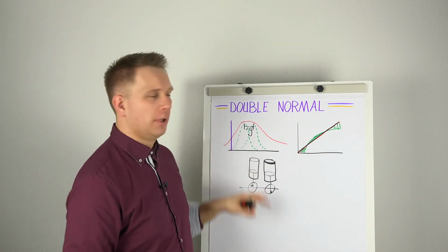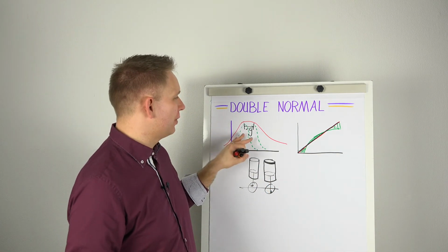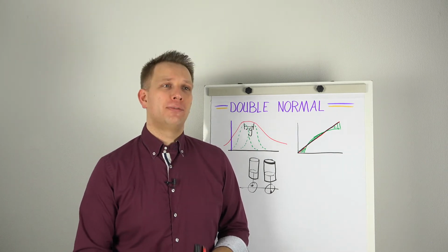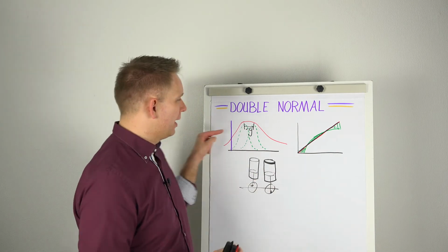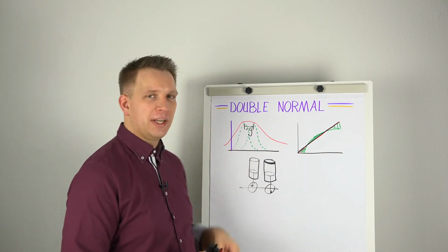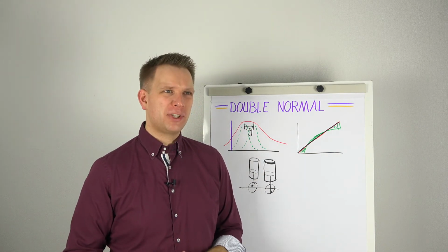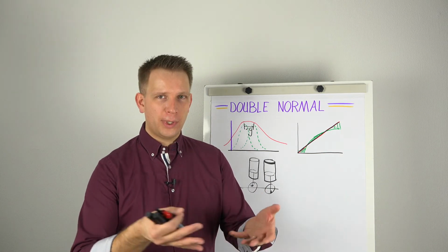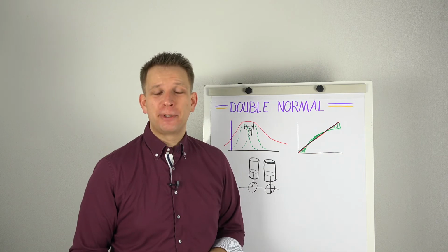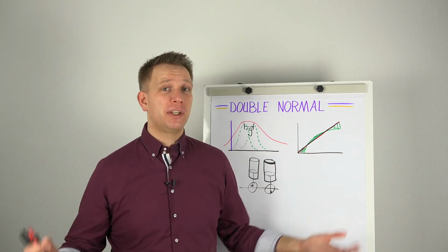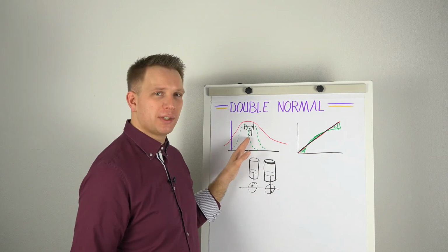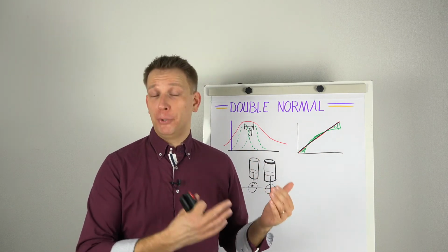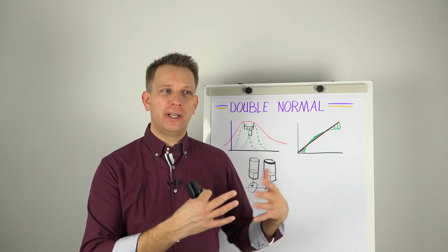And I thought it would be nice to share it with you: be on the lookout for a hidden double or triple or more, a double distribution within your normal distribution. The first sign you will get is a very high standard deviation, much higher than you would actually expect, especially higher than when you're at the line weighing some products or looking at the parameters and they seem to be okay, but the machine tells you that there is a huge spread. There is a good chance that it is factoring in a secondary, but also normally distributed process.